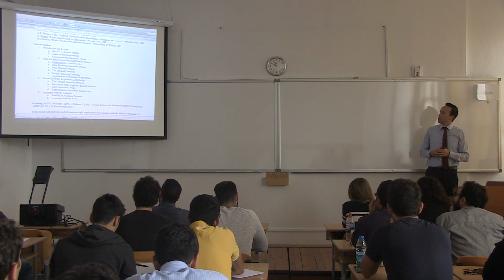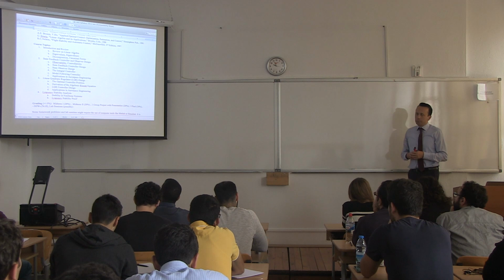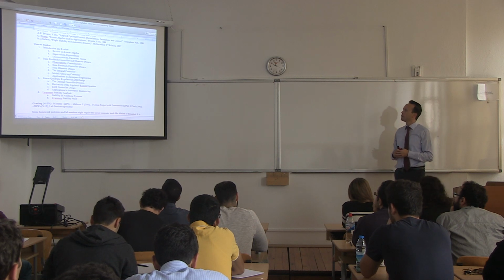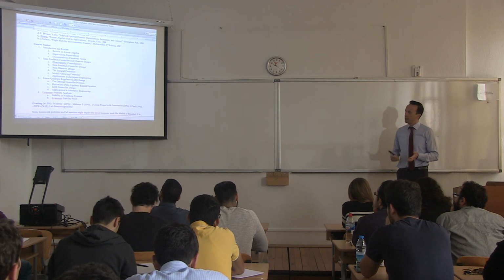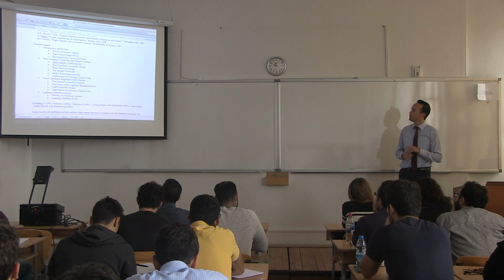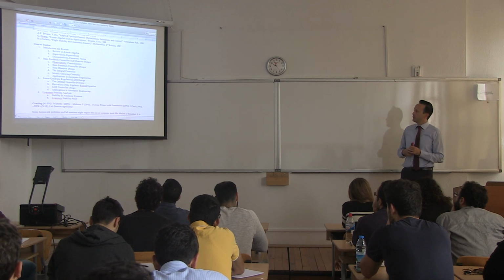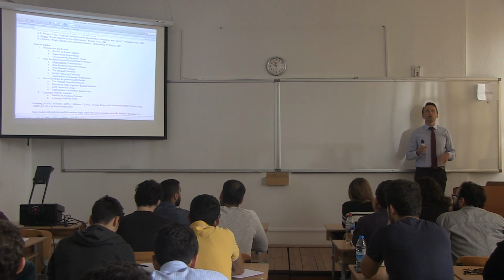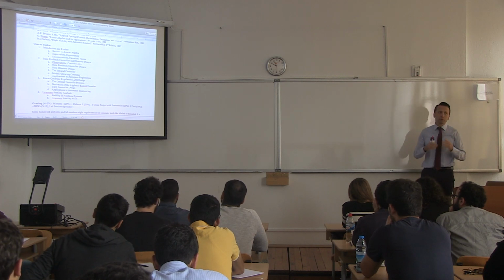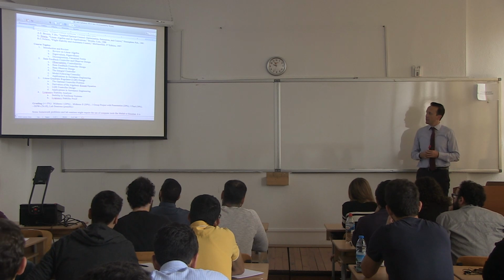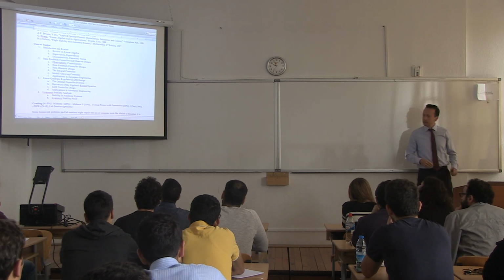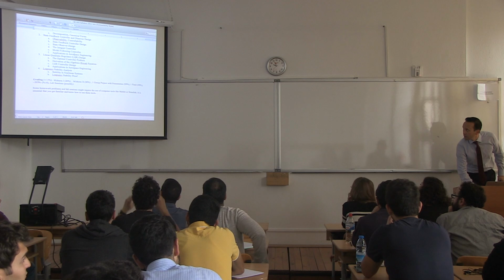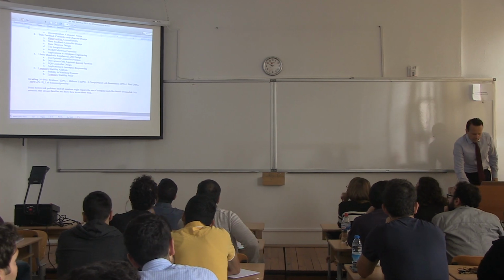Then we'll talk about the linear quadratic regulator, the optimal control problem. We'll look at the Riccati equation, the LQR controller, and finally we are going to go a little bit into nonlinear systems just so you understand what real life looks like. And there we're going to look at Lyapunov stability analysis. So this is kind of the syllabus.